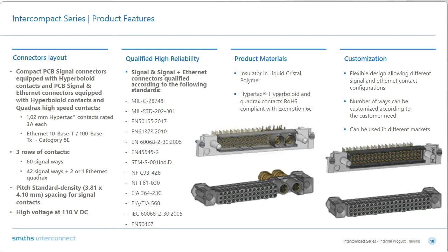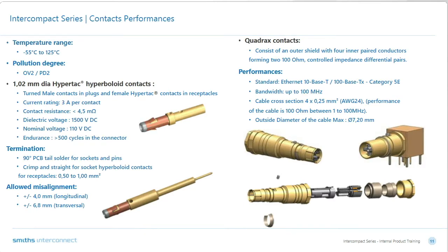When it comes to the temperature range, again, I must draw your attention to the specification of -55 degrees centigrade, because most of the specifications of what's available out there in the market, classified as connectors for arduous applications, are typically around -40 degrees centigrade.